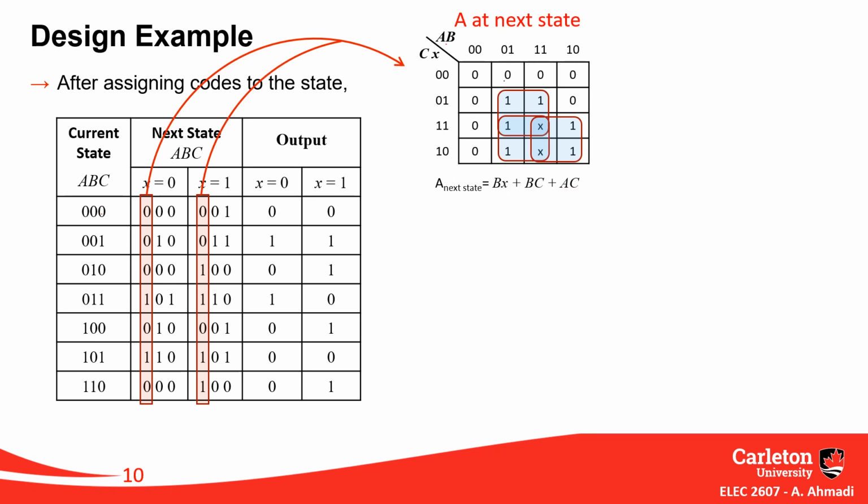I'm going back before I did that. Again, look, current state, inputs, value of the output, which is Y. This is Y. We find out what is the value at next state and output value using current value of the flip-flops and input using a K-map as this.